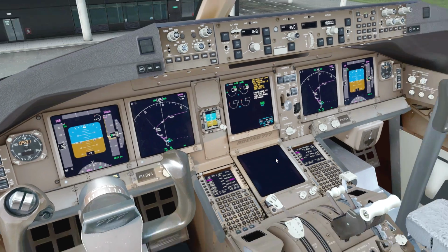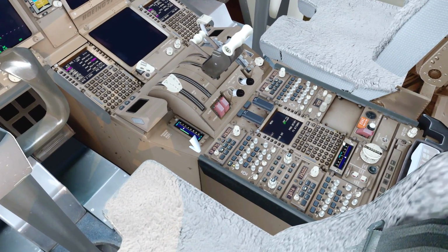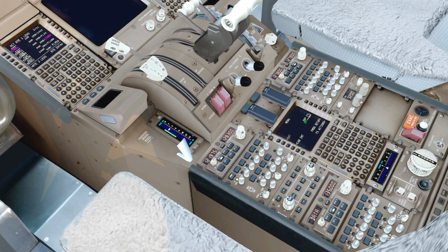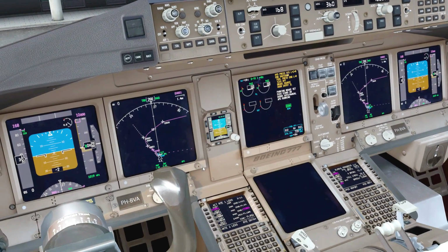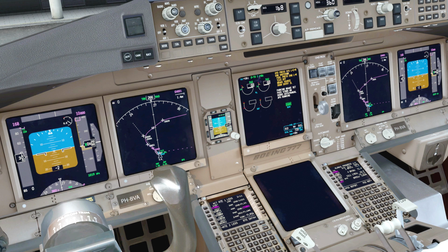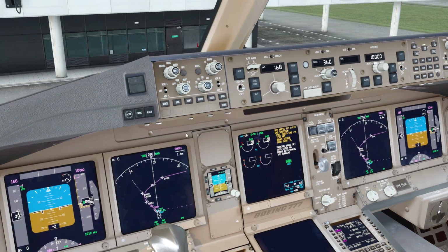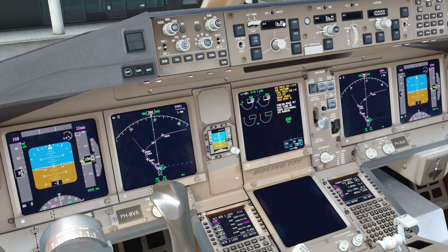Basically what you want to do then is, for example, enter a squawk code first of all. You will receive that from ATC, and then you can just put that right here in the transponder. And you also want to review the SID, kind of do a departure briefing for yourself, know which city you're flying, what way you're going, and then you can adjust the mode control panel for that.